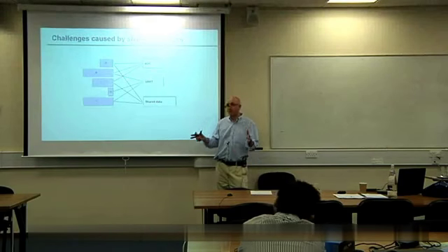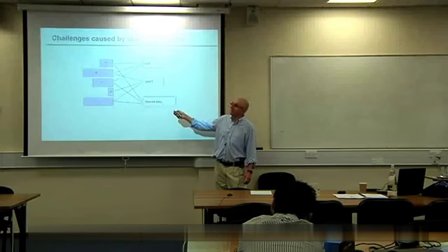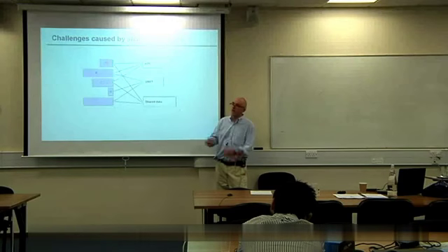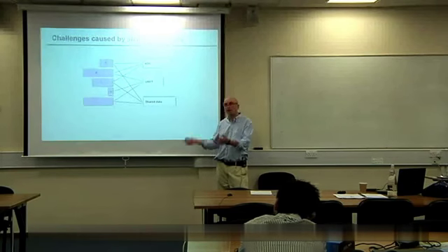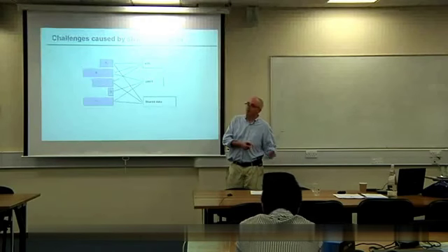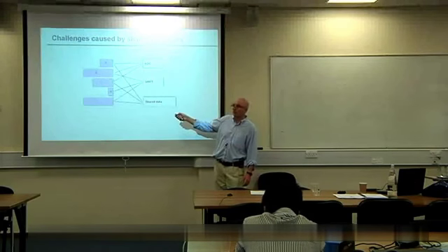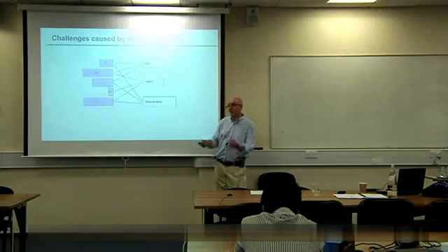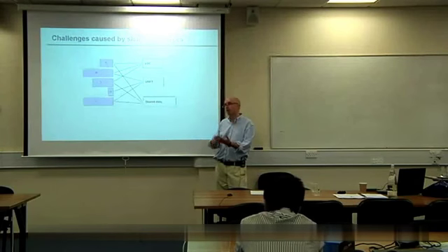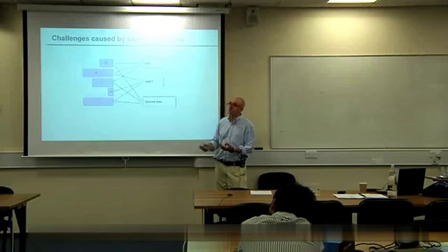So it's configured the ADC and it's about to do a conversion. Then it's interrupted by A. A sets up the ADC to read from channel 1, does its conversion because it's higher priority, and then returns and leaves the ADC again, completes. Then this one runs, and this one basically has set up channel 2, set the ADC to start converting, then it's been interrupted. But it doesn't know it has been interrupted.